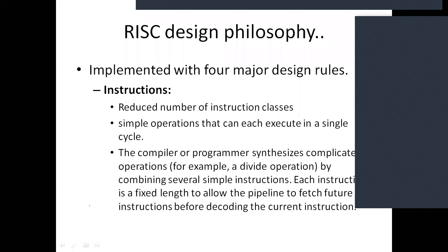So suppose the instructions of a processor have a variable length, for example, if the processor instruction is of 64-bit, in that case, that instruction has to be fetched 2 times because the instruction length is 64-bit. In the case of the ARM processor, this is a 32-bit processor, all the instructions are 32-bit wide.